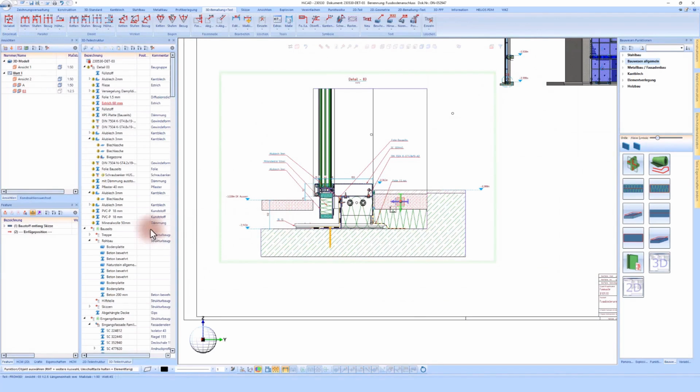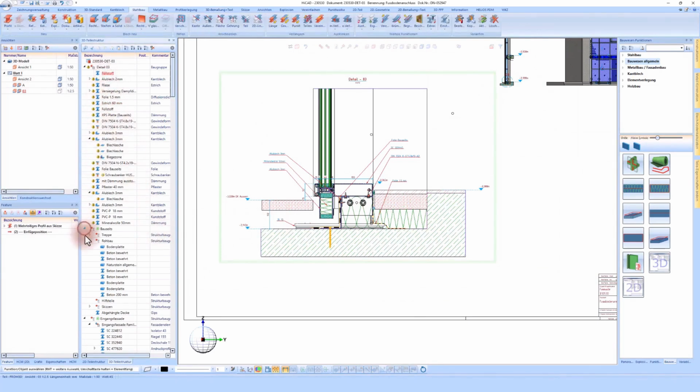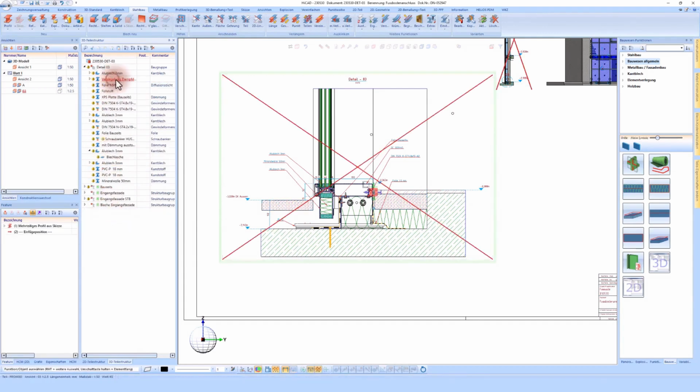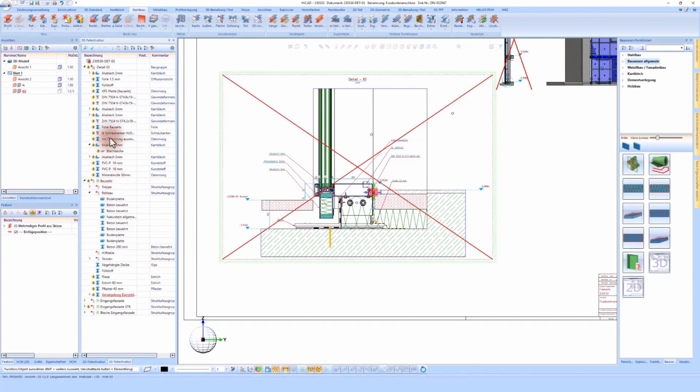However, what is important here is that I have simply modeled this area without paying attention and quickly created the part. This part is only visible in this detail. But I would like, of course, that if I have more details, these parts are also visible in the other parts and comprehensively. That means, for this reason, I will also pull these parts that I have integrated here into the external references so that they also appear in other constructions.